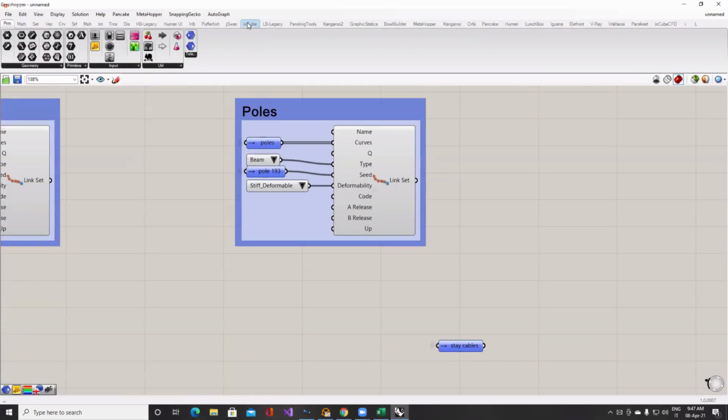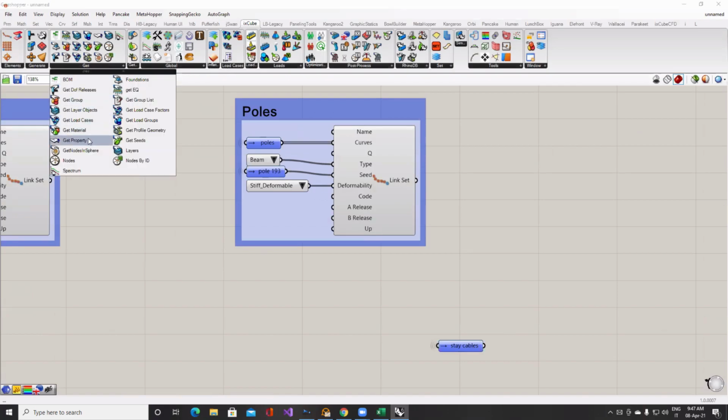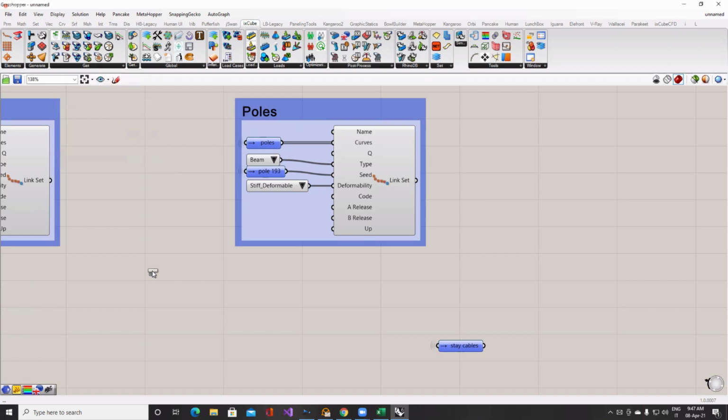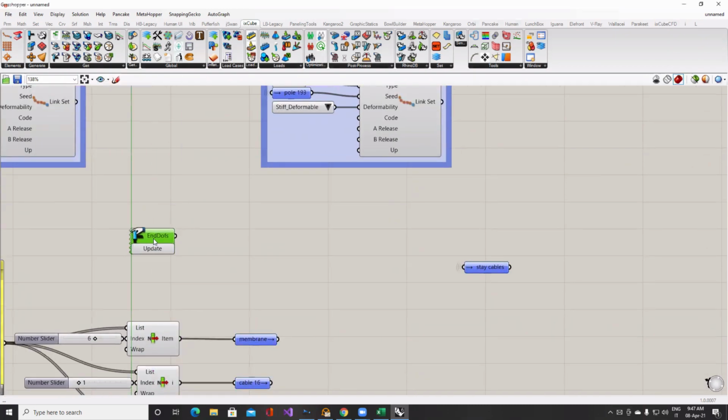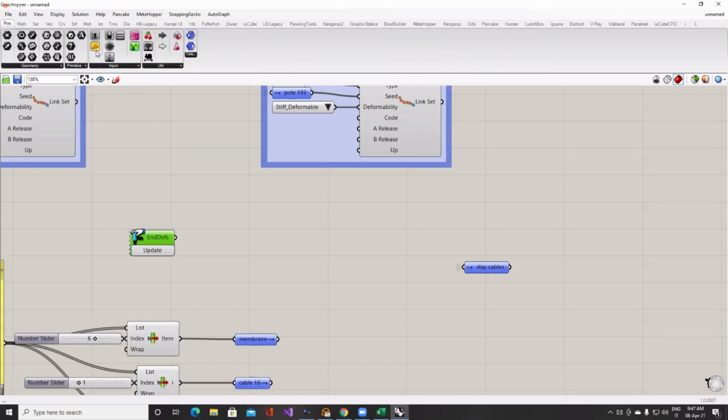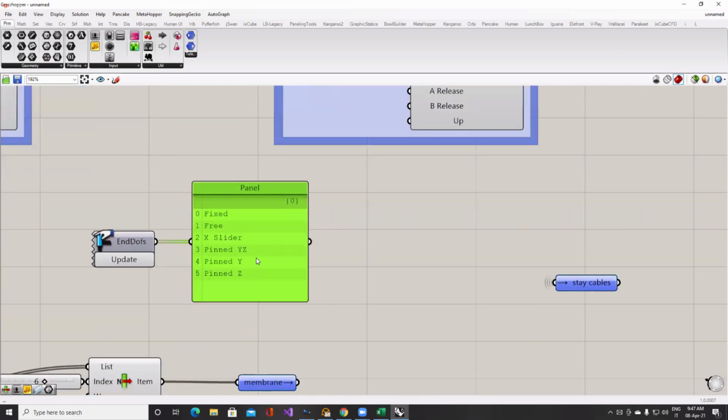If we go back to AX3, we can get the DOF releases. What are the DOF releases? We input this in a panel so I can show you. This is a table of end beam releases. This is the connection between the beam element and the node. Any beam element has two nodes. The first node, node A, and the end node, node B. The connection between the beam and the node has 6 degrees of freedom. So there are 6 connections.